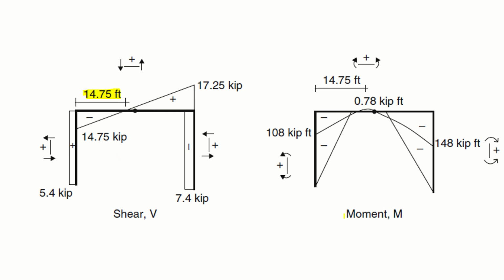Drawing the bending moment diagram, as you can see, these were hinge supports, so zero bending moment. This was a hinge support, so zero bending moment. This was an internal hinge, so zero bending moment. So all the bending moments at the hinges were zero. This is the bending moment diagram, this 1 degree line for this column.